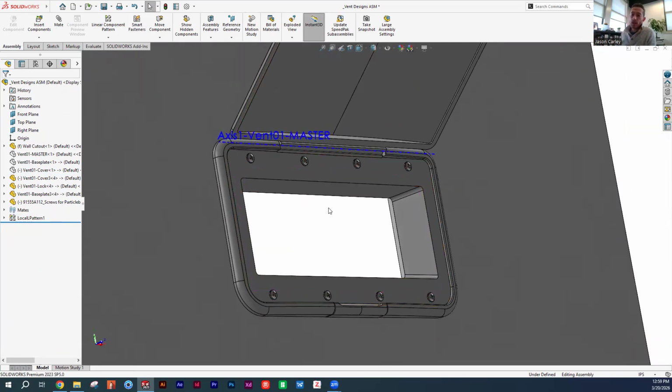What it also does is, SolidWorks and working with CAD makes assembling parts much easier than in KeyShot, which just uses positional coordinates. So it takes a long time to get something perfectly aligned in KeyShot if you're importing it without these mate assignments. So I can assemble something in SolidWorks, bring it in KeyShot, and then everything is aligned.